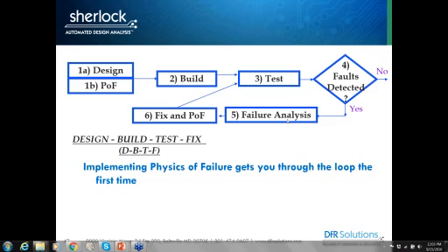There's a follow-on question on combined loading for solder joint life prediction. Because what we're looking at is multiple FEAs, and the finite element runs in Sherlock are relatively quick, on average 10 to 15 minutes for each type of vibration simulation in Sherlock.